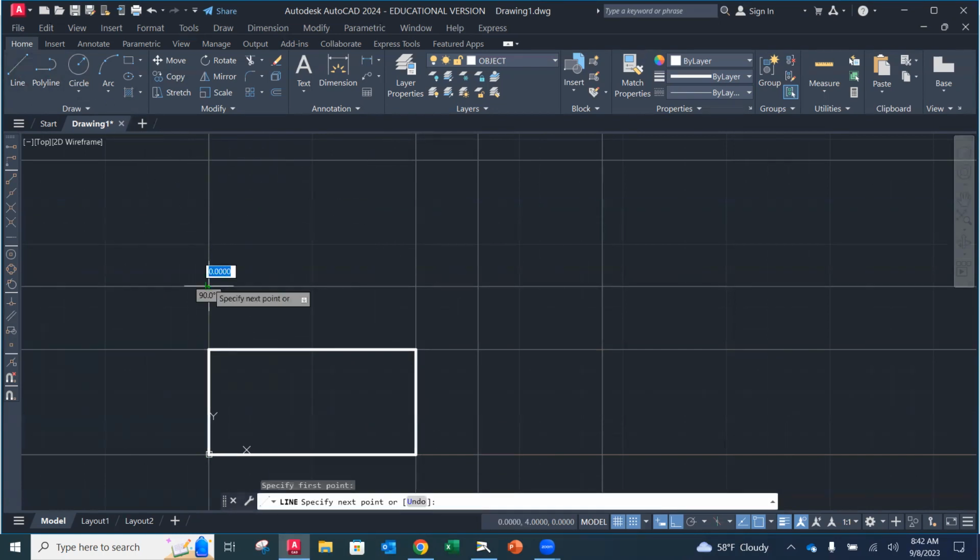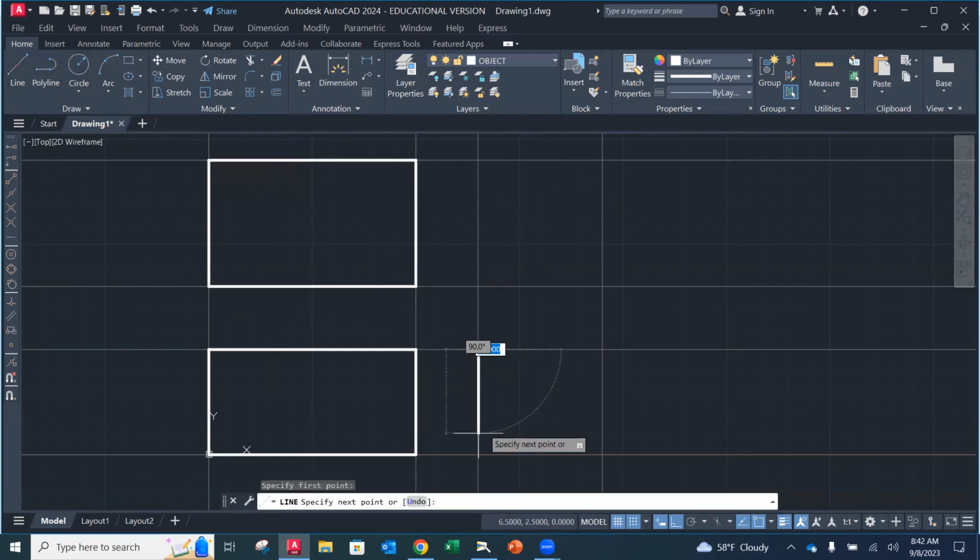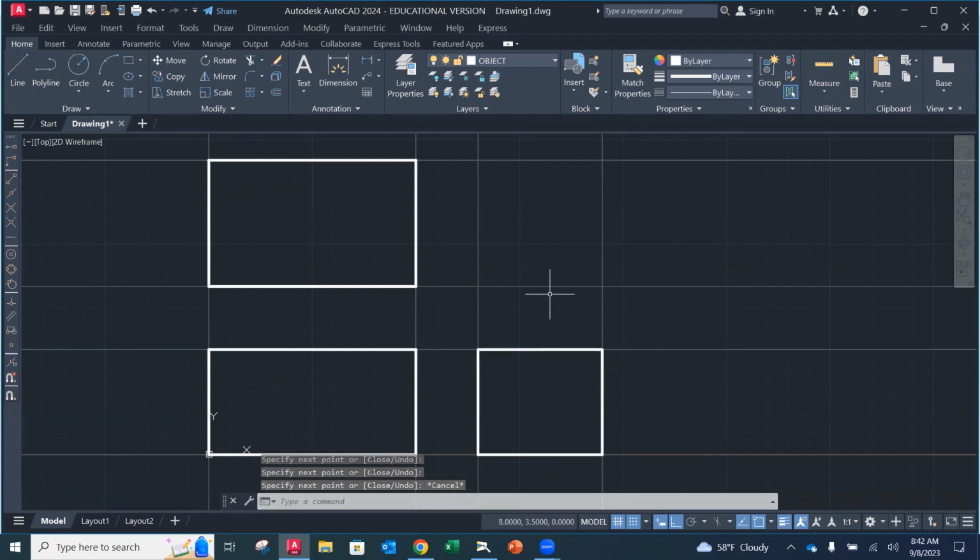So line. So you're going to notice now that because the line weight for the object line is that 1/2 of a millimeter, notice how much thicker it is than the construction line, which was default. Okay, it kind of helps you to see that my object lines, remember, are the most important lines in the views. So they are going to have a thicker presence.